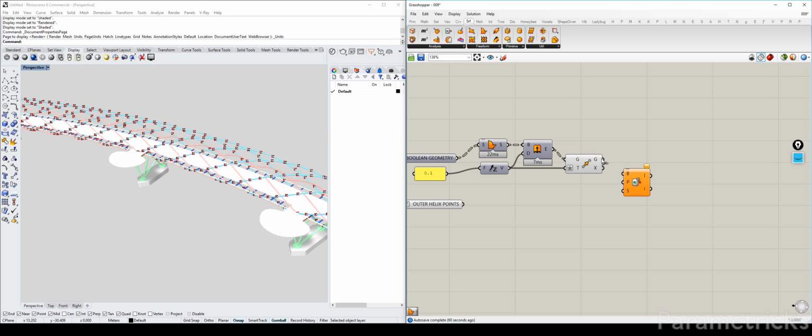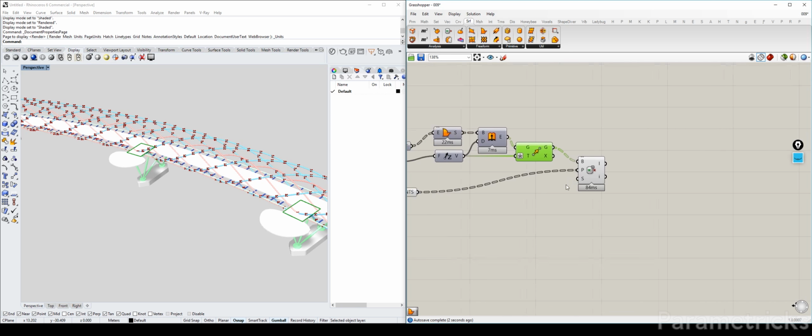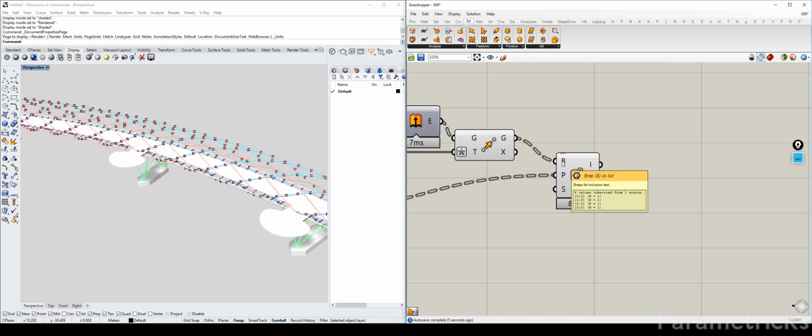It has 3 inputs: the BReps themselves, and the point, and this is that strict Boolean that I was talking about, but I would rather not rely on it than just move. It doesn't cost you that much computational power just to move your geometry back down a little bit in order for you to get a better result. So let's connect these two together. I'm now seeing an error that we might encounter, and that's because we have 4 branches that will act only upon the first 4 branches here. So that's not going to give us a correct answer, and that's not what we want.